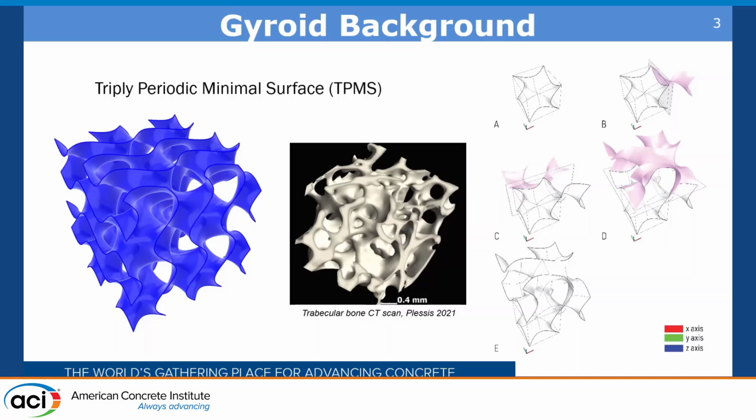This is largely because, as stated previously, the gyroid is extremely efficient under compression in all three directions. It's able to effectively distribute loads across its sinusoidal curves, shown here, and this allows it to carry a high load across a larger volume than would normally be possible, limiting the amount of material that is needed.